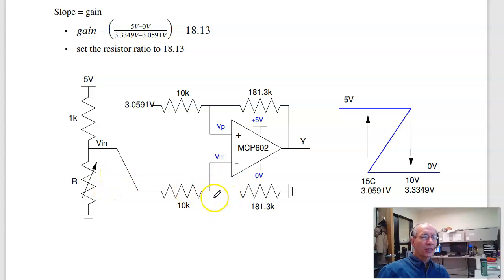Make this large, and it's not too bad. So like this affects the resistance by like 1%. So my numbers are actually about 1% off. If you want to be dead on, what I could do is add a buffer. A buffer is just an op-amp circuit going like this. The input impedance to an op-amp is about 4 gigaohms, basically no loading, and then you'd be more accurate. But it adds another op-amp. So that's problem number 2.